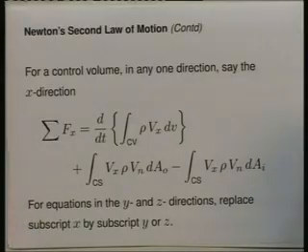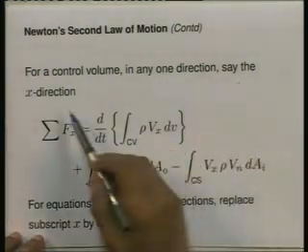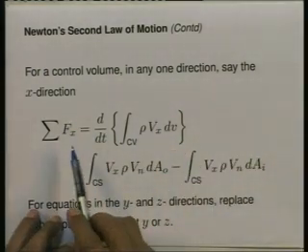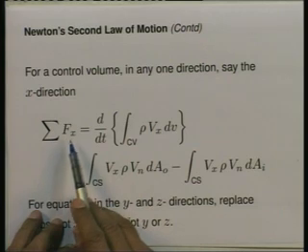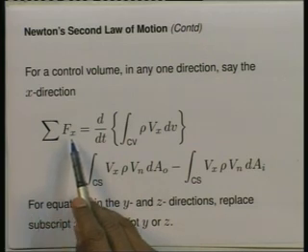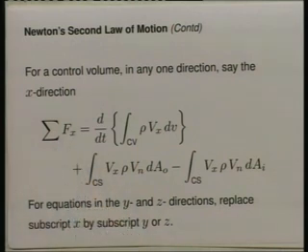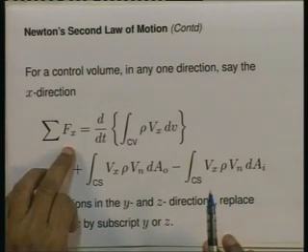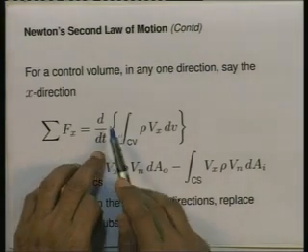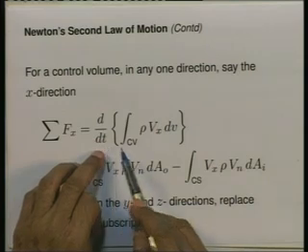For a control volume in any one direction, say the x direction, the statement of Newton's second law would be: summation F_x, all the forces exerted on the fluid inside the control volume by the surroundings, and their x components, mind you. So summation F_x equals the rate of change, d/dt, of...